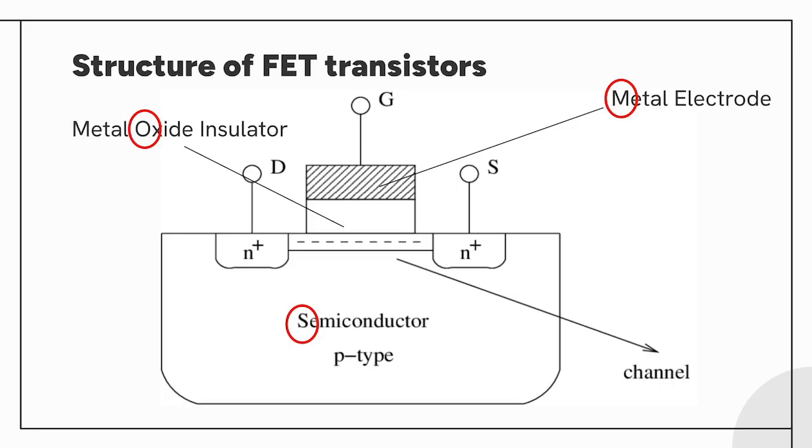This picture is the structure of an N-channel MOSFET, a type of MOSFET. In the case of the N-channel MOSFET, a P-type semiconductor with a lot of holes is used as the substrate, and on top of it, insulating material, oxide, and metal form a gate, and on both sides of this gate are the N-type doped source and drain with many electrons.